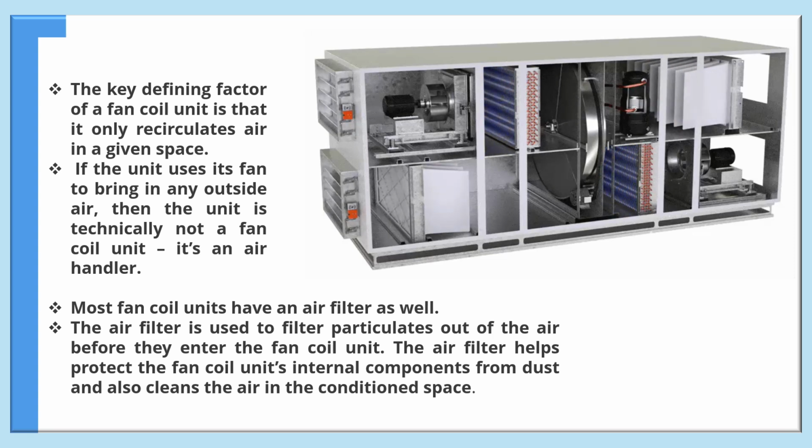Most fan-coil units have an air filter as well. The air filter is used to filter particulates out of the air before they enter the fan-coil unit. The air filter helps protect the fan-coil unit's internal components from dust and also cleans the air in the conditioned space.